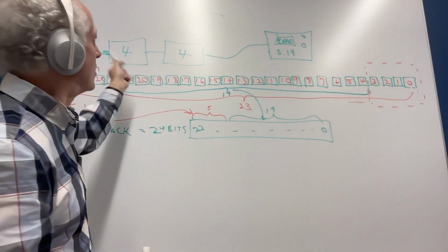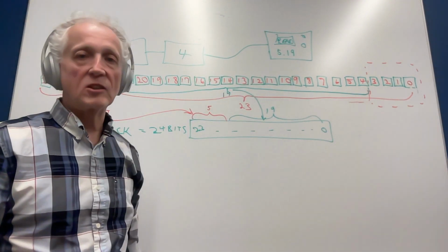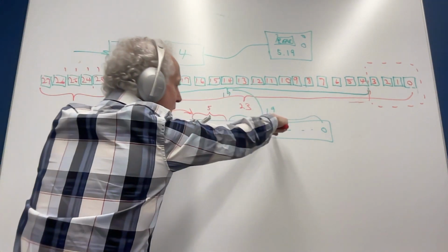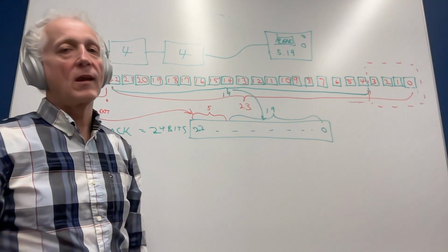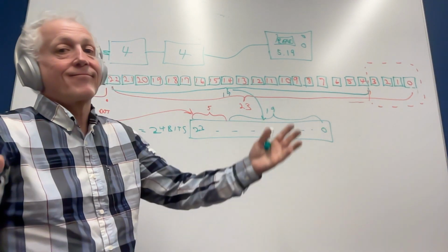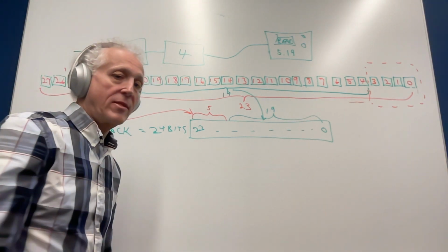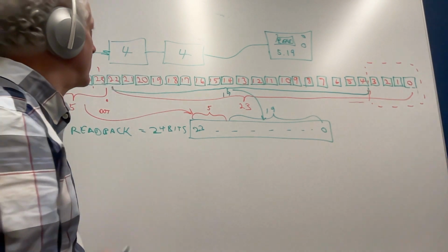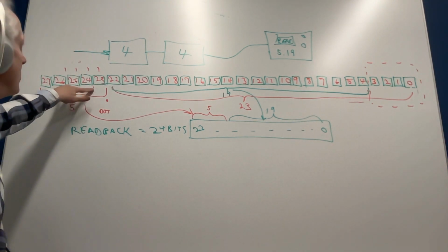And so you multiply by 16 and then send it to the read back. So this would shift the data over by 4 and then shove it into that 24-bit location. So that's the little tricky, dirty little secret there. Sorry about that, but that's the way it is, and that's how we can end up multiplying by 16, get around the problem of only having 4 bits.